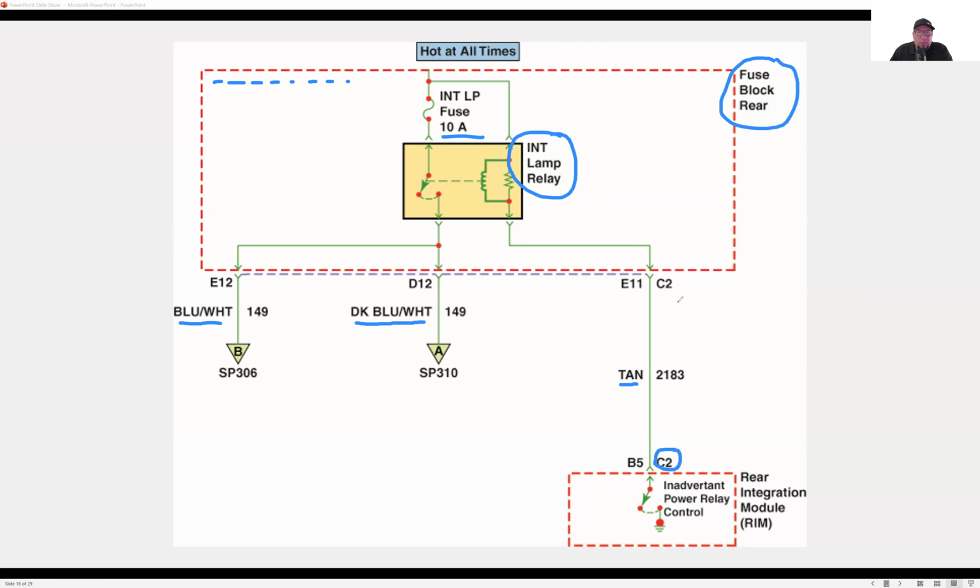Okay. Again, I'm just getting you guys to understand how to read these. Again, some of these we're gonna have big connectors on some of these units and some of these modules, fuse boxes and stuff, and these numbers just relate to the connector numbers. Okay. Each terminal number. So there's a connector number, there's a terminal number within the connector. Again, it gets somewhat complicated, especially when you're dealing with a connector that has 80 terminals in it, then yeah, it can get very complicated. But for the most part right now, I just want you to identify some of the common parts, some things that pop out to you right away and what you see. Okay. I don't expect you to become an expert on this right away.